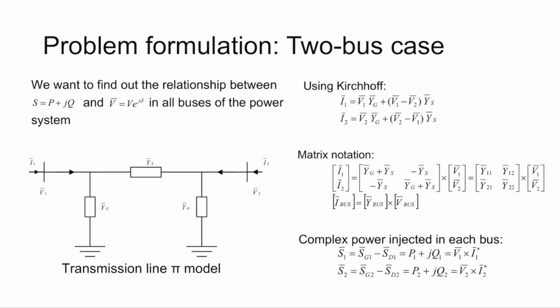For calculating power in node 1, again, this is injection power. So it's equal to this active power plus reactive power, this complex number. And remember, this is V times I star, star representing the conjugate value of the current. And as I mentioned, this is a generic node or generic bus. So it means I either have generation or demand, or maybe I have both of them. So I will represent this injection, this S1 is just the injection, as positive for generation minus a negative demand.